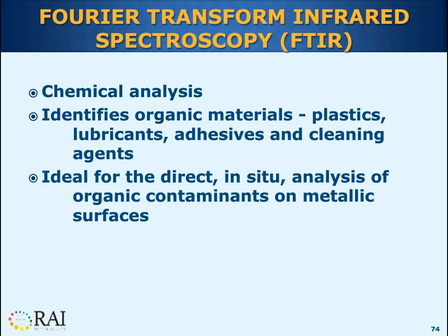FTIR can help identify what type of contamination might be contributing to that, be it oil that was not removed prior to the painting step. If it's a plastic part, there could be drawing lubricants on the plastic part to help draw the part. Many times these lubricants or oils are difficult to remove, and if they've been on there for a long period of time, they tend to oxidize and become extremely difficult to remove.